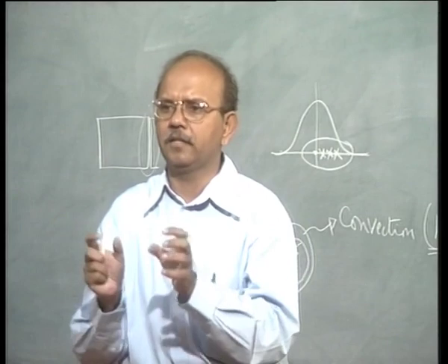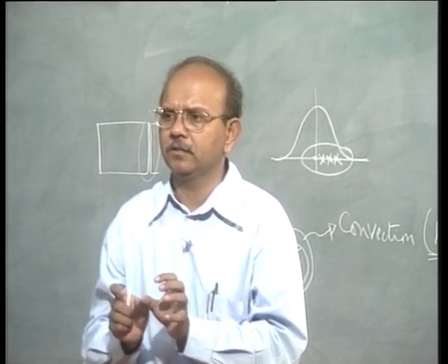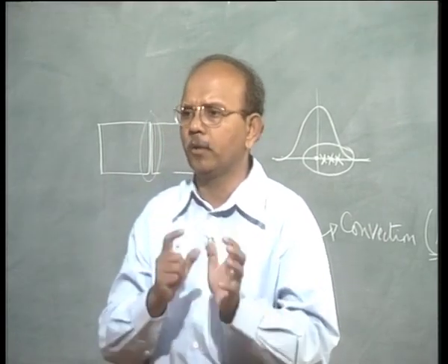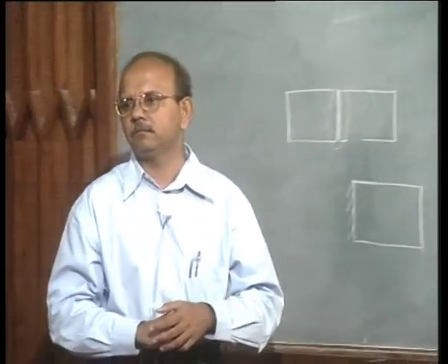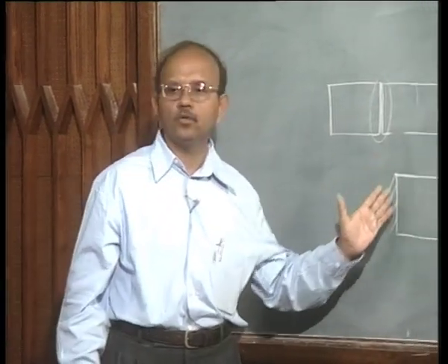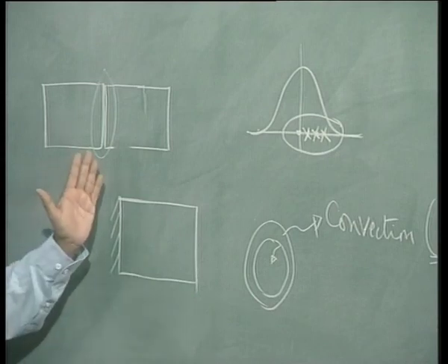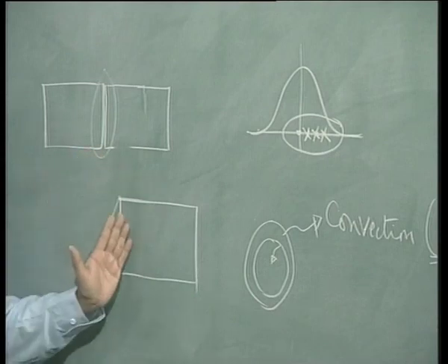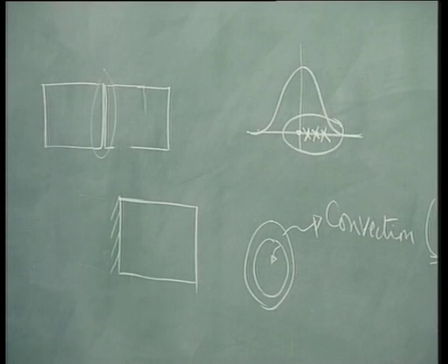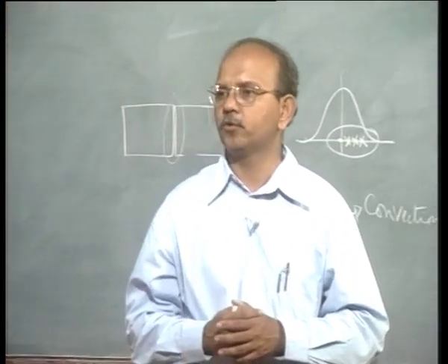Suppose they are flush, one against the other, they just touch each other, then how do I put the boundary condition? Boundary condition is now very simple. Then you put this and so on, okay, you just fix all the nodes which are sitting in this plane, be done with it, because there is a symmetry boundary. In fact, what boundary condition would you put? You would put a symmetry boundary condition, but is it correct to put it like that?